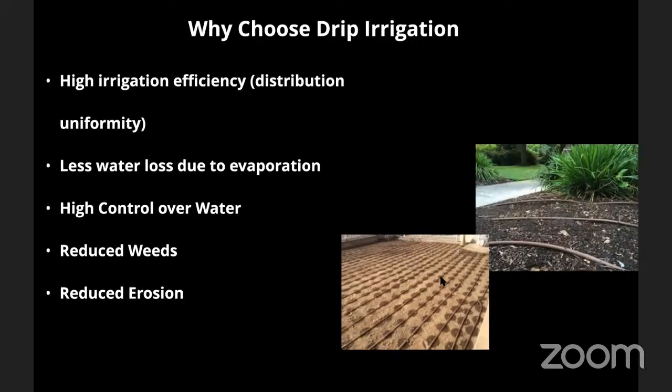If you have a landscape area where one section, for example, has fruit trees and then immediately next to it you have low water plants, with a spray system there'd be no way to give each section of the garden just what they want. With drip irrigation, because the tubing is flexible, you can set up one area to be higher water, one area to be lower water next to each other.